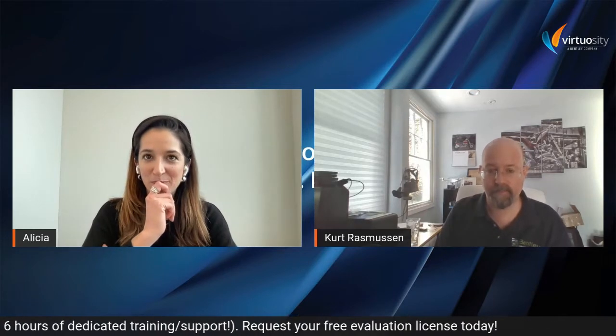I took some of my knowledge from doing volume calculations for things like ground, and I've done some walls after the collapse of Ground Zero at the World Trade Center. I created a model of the slurry wall, so calculating volume there. Things like that, we laid it on our back and did contouring. But in this case, with 3D models now, I can just model it right at its face and start to look at some values there.